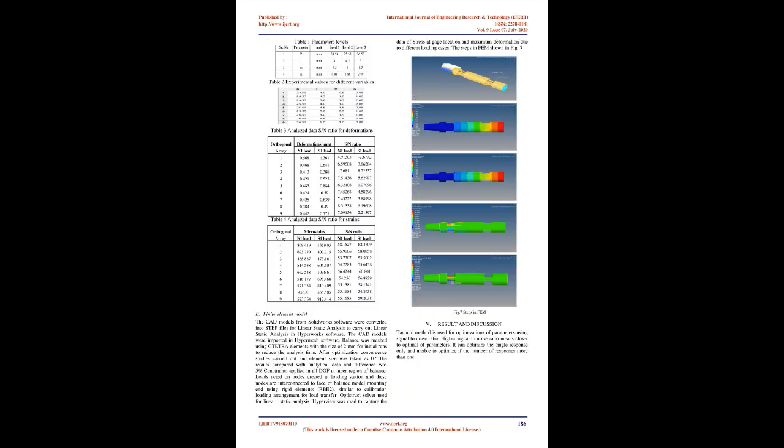The balance has various sections as shown in Fig. 3 and Fig. 4, such as mounting end, grounding end, side force, and lift force. The goal is to fabricate a balance in which the selected section is sensitive in the direction of the considered component and insensitive in the other directions. This objective can be accomplished through the proper design of the sections and appropriate wiring techniques.